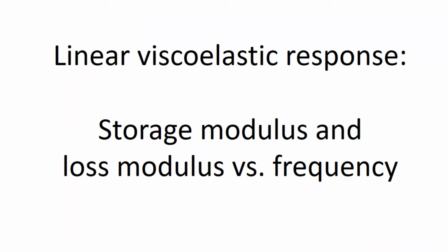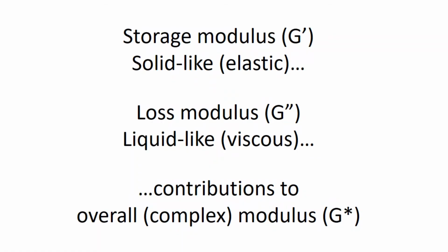So next in the guidelines we see linear viscoelastic response, storage modulus and loss modulus as a function of frequency. When we oscillate at very small stresses, we operate in what we call the linear viscoelastic region for the material. The storage modulus and the loss modulus are just the elastic and the viscous, so the solid-like and the liquid-like contributions to the overall rigidity of the sample structure. If you want a simple but very unscientific explanation of storage and loss modulus, then you should take a look at my video, Storage and Loss Modulus for Beginners.